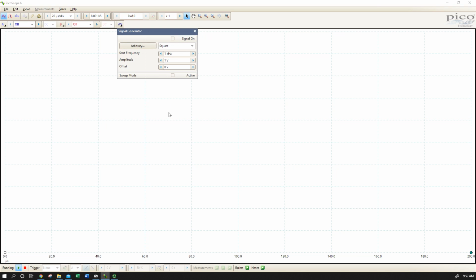100 ohm resistor. Now, one of the nice things is we're not going to get a dead short at resonance either. So that gives us a little bit more flexibility when we're scanning through our resonance circuit. We don't have to worry quite as much about having to include a current limiting resistor, which is why I'm able to use a resistor as low as 100 ohms for this series circuit.